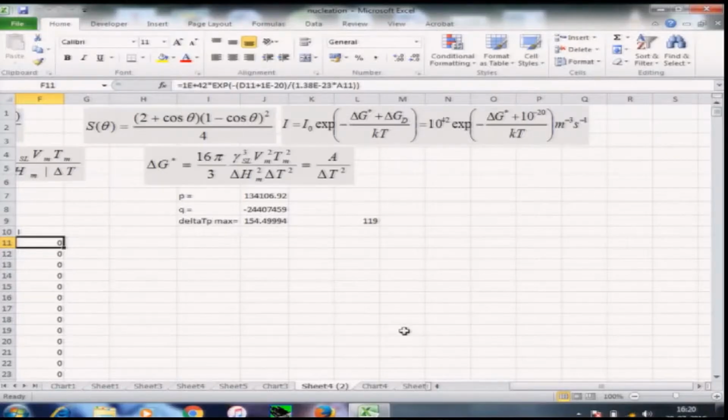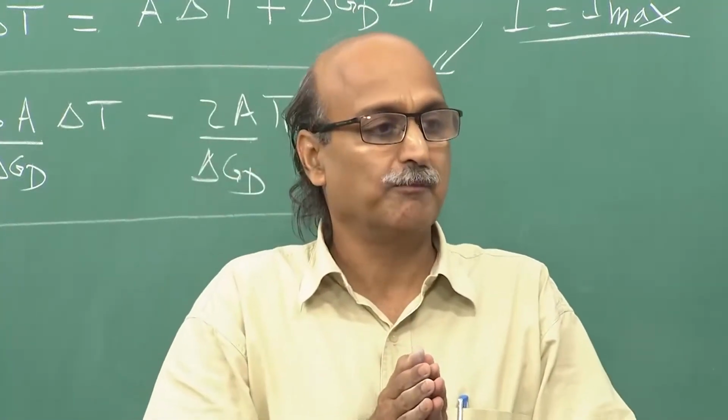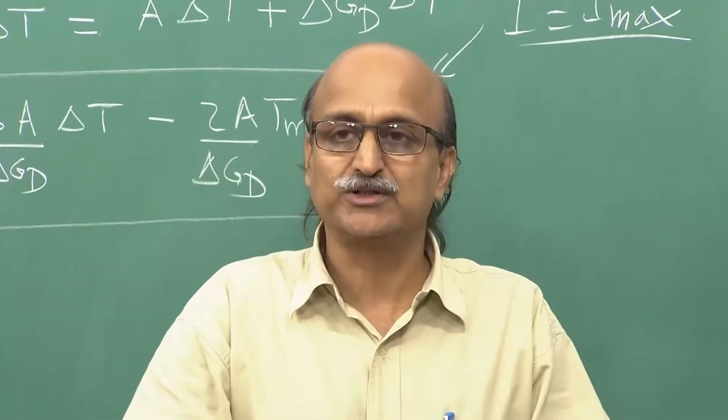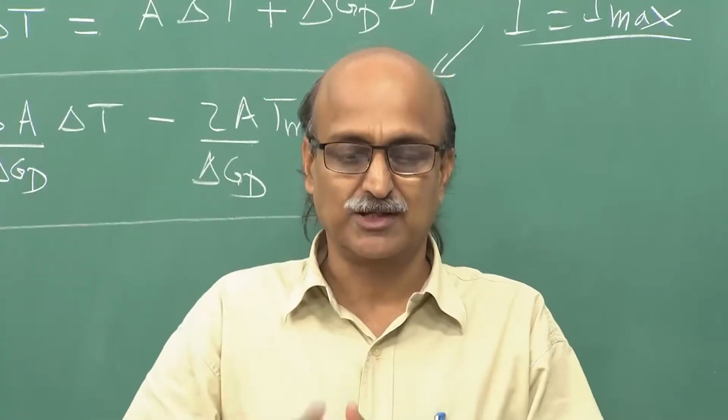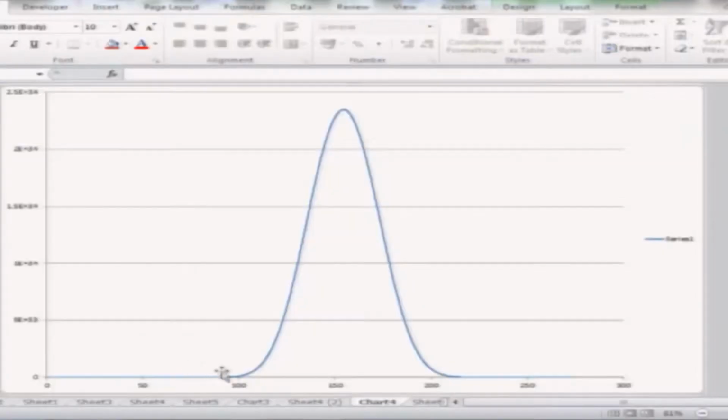So, there is a trade off. As the temperature goes down, the mobility of the atoms goes down, but the driving force for nucleation is increasing. These two opposing effects initially lead to an increase in the nucleation rate, which goes to a peak and then starts to drop again.